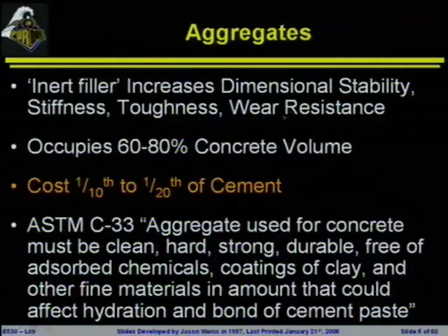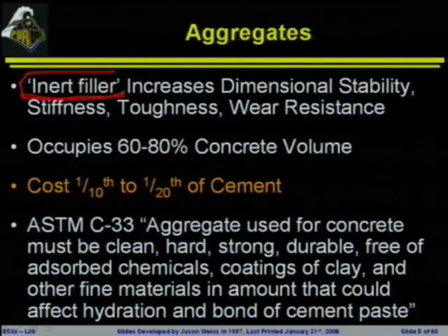Now, aggregates or rocks are a quote-unquote inert filler. And I say inert because what you're going to find out as we keep talking about here is the best that you can hope for is the aggregates to be inert. The best that you can hope for is for them to sit and sleep for the rest of the concrete. If they are not inert, if they are going to be reacting with the cement, they're going to be reacting with the alkalis, you're going to have a big problem. All right, so we're hoping that they are inert. We're hoping we're not going to have freeze-thaw problems. We're hoping we're not going to have an ASR problem. They are an inert, relatively inert material.